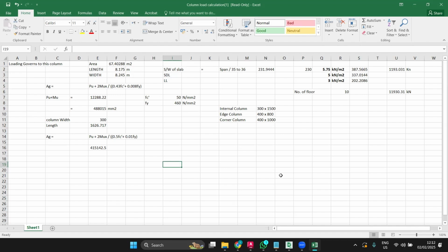Whereas if you're increasing 25 millimeters of your core wall, it does not have such impact, because those 25 millimeters I can increase inside the staircase, even on the corridor side. You're getting the point. Touching your columns, how much impact do you have, rather than increasing your shear wall by 25 millimeters? The beauty is, now it is 300 by 1500, is it a column or a shear wall? That also you need to understand.